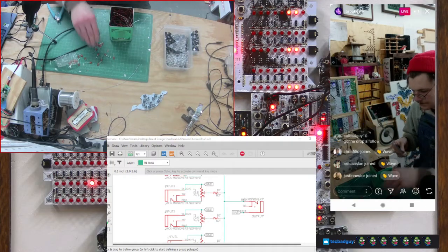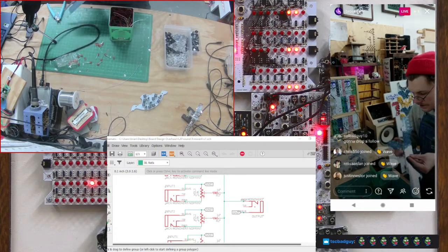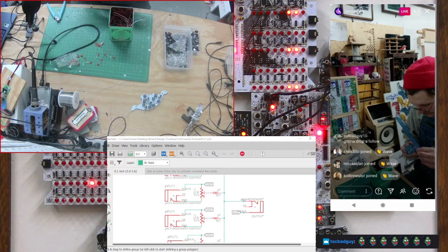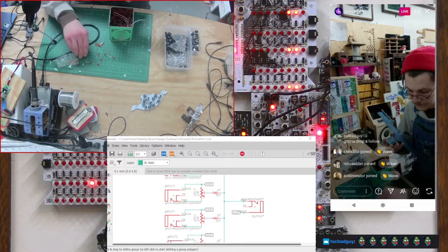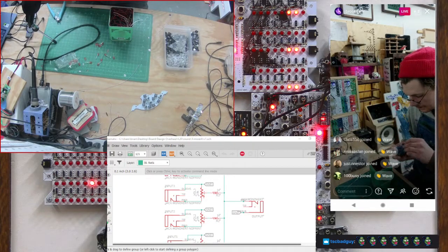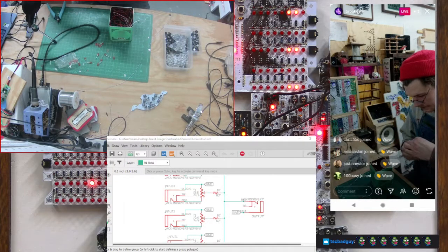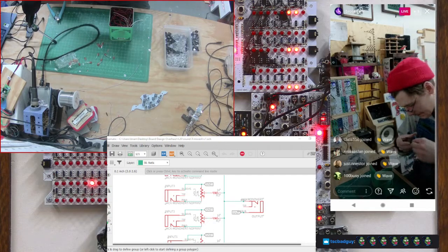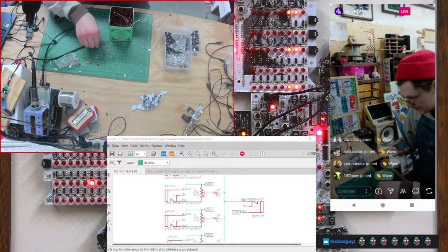cause enough to, because it's not something you ever notice. It's just something you have to remember when you're building it. Otherwise, none of them will work, because LEDs are polarized, which means they have a positive and a negative. So they have to go in a certain way. And if you don't, then they'll either just not work or they'll get fried and then they will never work. Yeah, for this one I sort of decided that backwards LEDs wasn't that big of a deal.